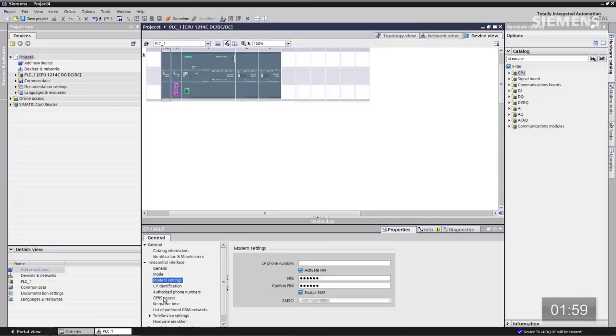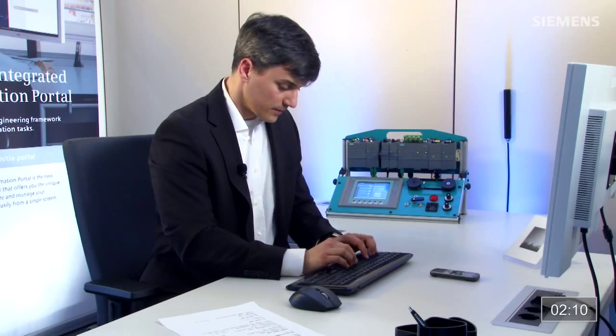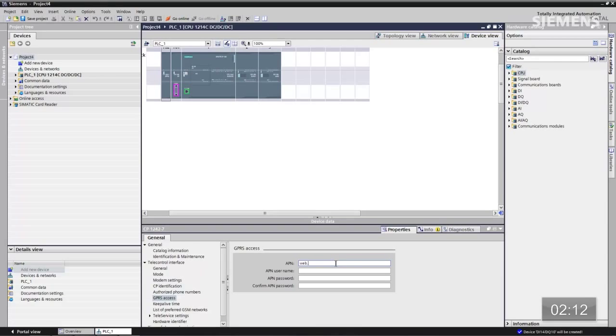Okay, so the first step for that is now complete. We can move on to the GPRS access. One thing we need to add is the actual provider's web address so that we can make certain that we've made a connection to their SMS server. So that happens to be web.vodafone.de. And last but not least, go and look to see what hardware identifier we've been given from this configuration. It happens to be 277. Just remember that for later.